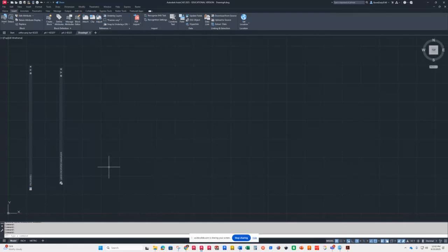All right, so for 4-3, you're going to do a front, a top, and a left side view because it's facing towards the left. That's our plan. So it has a long side, therefore that's probably going to be the front. So the 4 inches, which it's inch, so that tells us that we don't need to change our limits, because it's only 4 inches wide, 2 inches tall, and 1.75 deep. So we're going to do a front, a top, and a left side view.